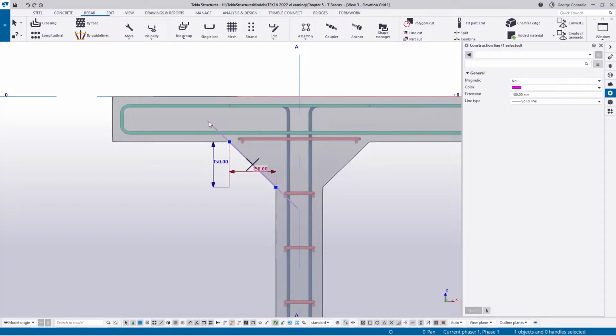If I click on it, you get this sort of grip. Now what you need to do, while you're moving it, is make sure that your vertical and your horizontal stay the same value to enable the 45, because you don't have a snap mode, because you're not in an XY plane, you're in the XZ plane. So if I just stretch, you can see 200 by 200. If I drift a little bit, that's 200 by 150. That's not 45 degrees, but that is. So that's a quick way to ensure that you are actually at 45 degrees.